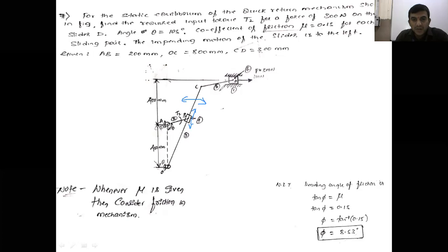At the same time, what happens? Link number 5 also moves like this, right? It also oscillates, and at the same time also moves linearly. What is link number 6? Link number 6 undergoes a linear or rectilinear motion, or reciprocating motion. That slider undergoes a quick return motion, right? For the cutting stroke, the time taken is more and for the return stroke the time taken is less. That's why it is called the quick return motion mechanism, right?